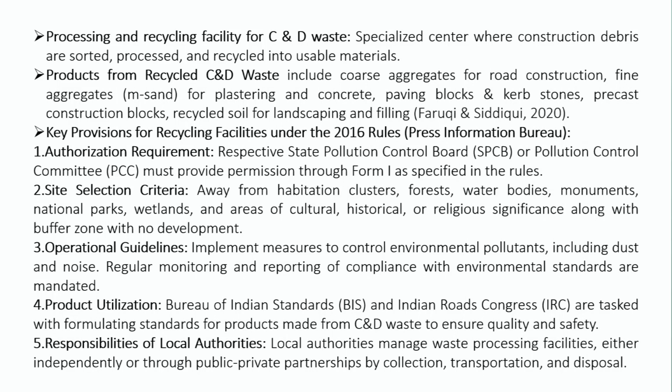Key provisions for recycling facilities under the 2016 rules. First is the authorization requirement. Respective State Pollution Control Boards or Pollution Control Committees must provide permission through Form 1 as specified in this rule. Second is site selection criteria: away from habitation clusters, forests, water bodies, monuments, national parks, wetlands, and areas of cultural, historical, or religious significance, along with a buffer zone with no development.